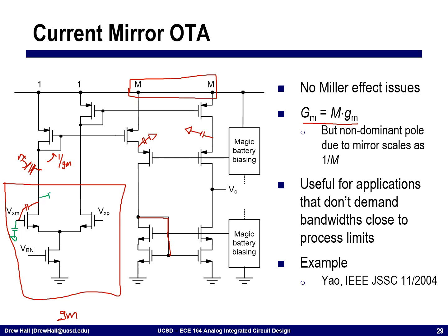In this particular case, the voltage gain in this first stage is actually quite limited. Okay. And so if we were to write out the small signal voltage gain of just this input stage, I essentially have GM from these devices, divided by the impedance that I see here, which is 1 over GM, which is equal to 1.